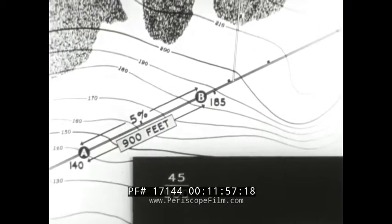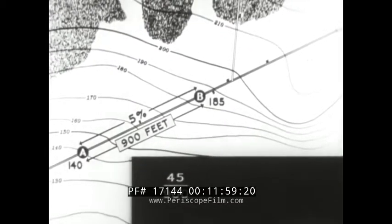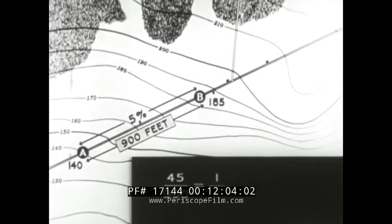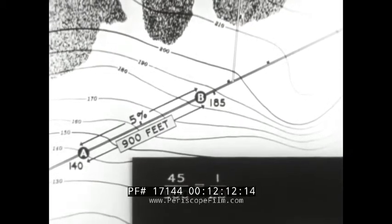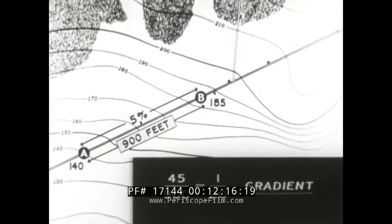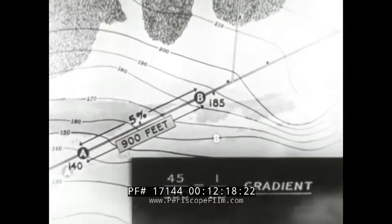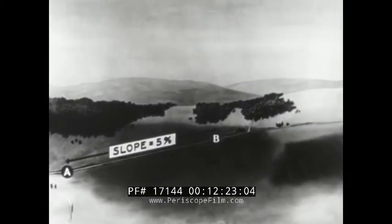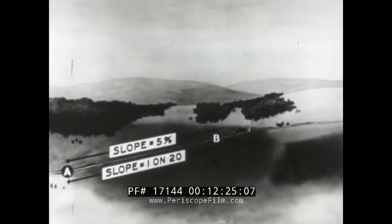The ratio of the difference in elevation to the horizontal distance, that is 45 over 900, reduces to 1 over 20. This is read 1 on 20. It means that a 1 foot rise occurs in each 20 feet of horizontal distance. This expression of slope is known as the slope ratio or gradient. Thus, a 5% slope is the same as a slope the gradient of which is 1 on 20.